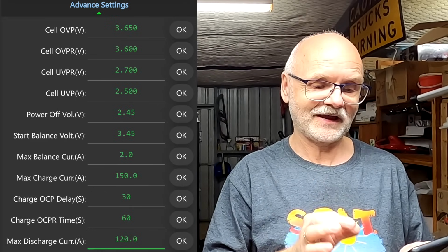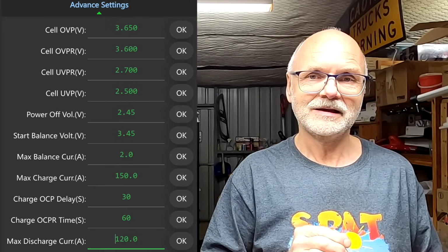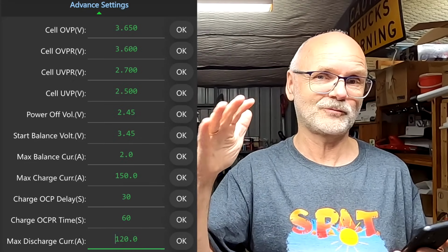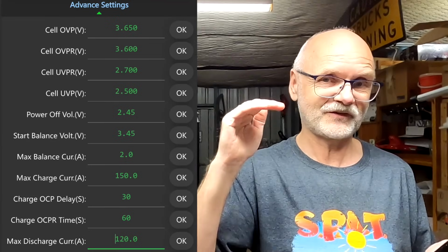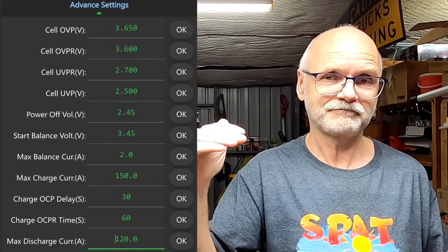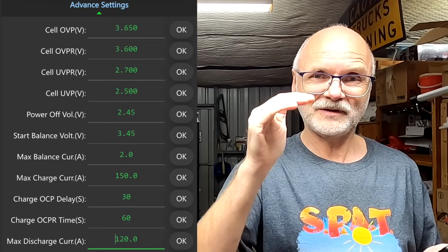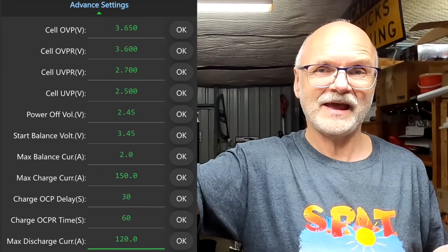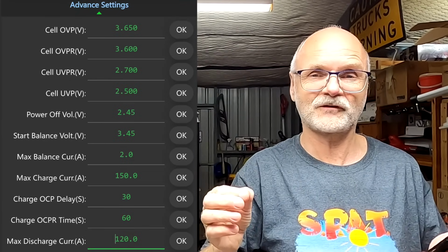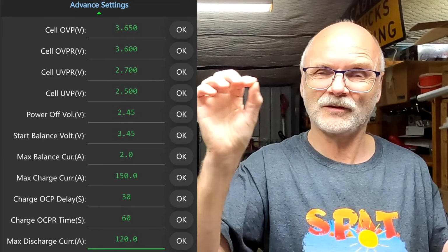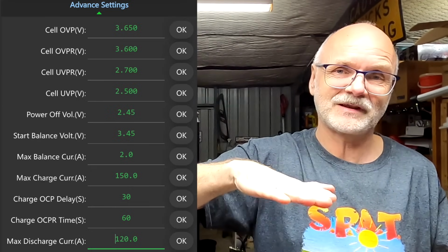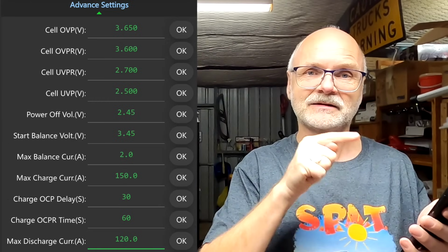And this is also the exact voltage when the balancer kicks in, because this is what I want to achieve. Charging to 13.8 volts would mean every one of the 4 cells in my 12 volt pack would be at 3.45 volts, ideally. If you have one cell a little bit higher, you want to chop off the head, right? You want to push this one down because it's too high. If it's at 3.46 volts, for example, just a tiny bit higher than all the other ones, you want to discharge the cell so the voltage goes down again. And this is exactly what the setting does.